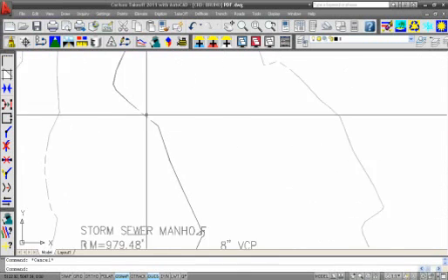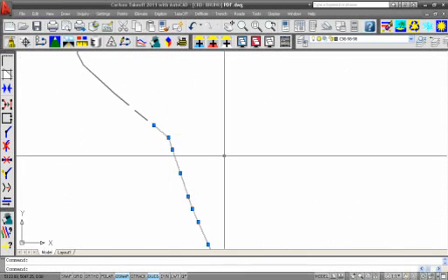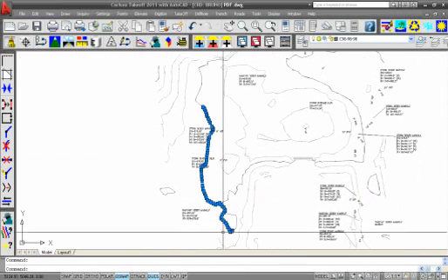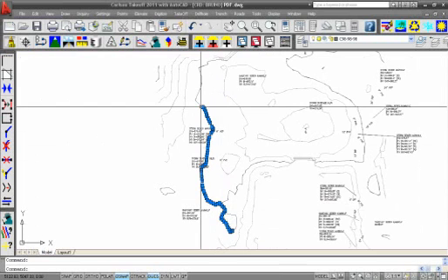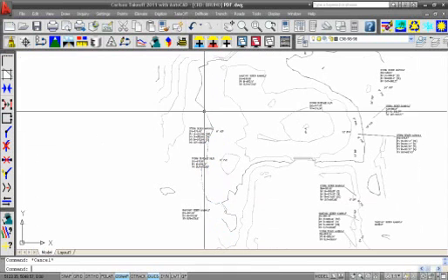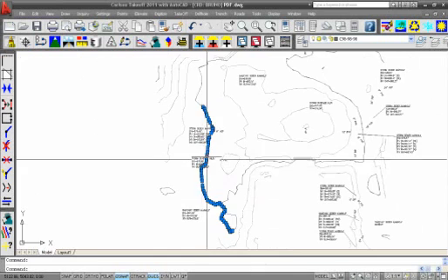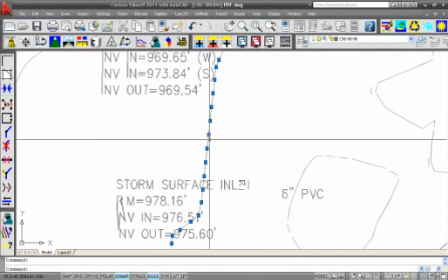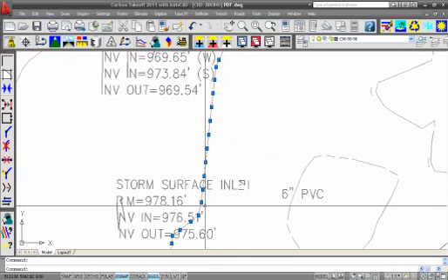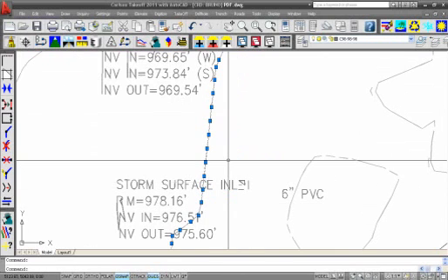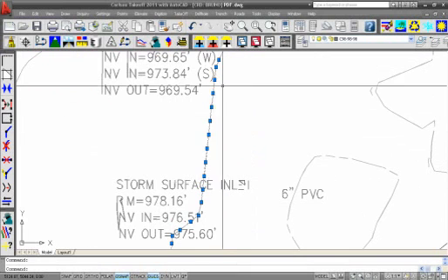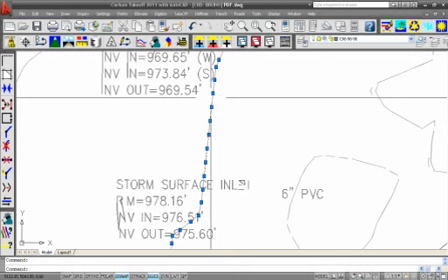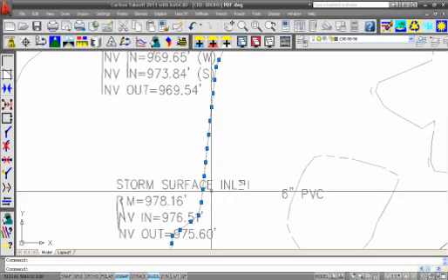Okay. Now, are those grip panels considered vertices? Yep, those are vertices on the polyline. So we can now go into drawing cleanup and reduce this file even further, so that if we happen to be wanting to take this all the way out to a machine control situation, we have faster, better results. Right. Okay. Yep. So drawing cleanup would probably get rid of a lot of the points along this line segment here.